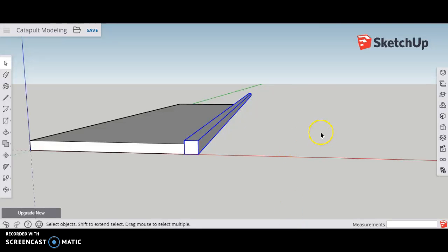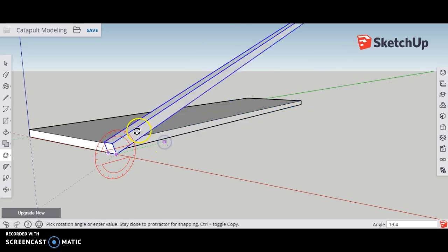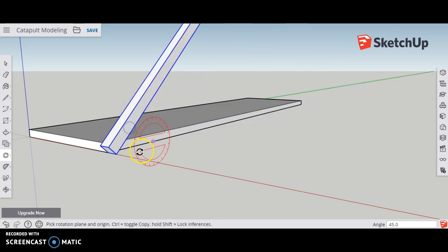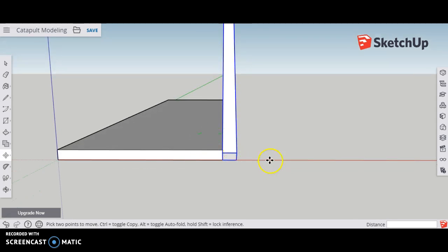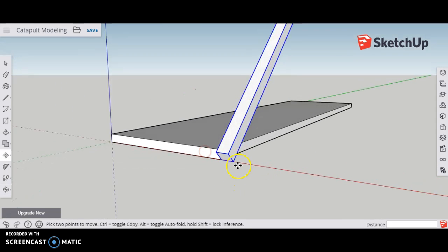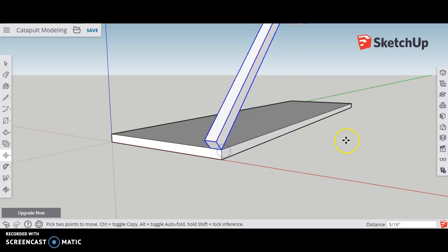Okay. Now with that done, I could of course rotate these beams. My rotate tool is over here in the suite with the move tool. I also like the Q for rotate. Note I can use my arrow keys to change the plane of rotation. Okay, so one option is modeling these things in 3 dimensions and then rotating and moving them where they need to be. I can move from this corner to that corner.